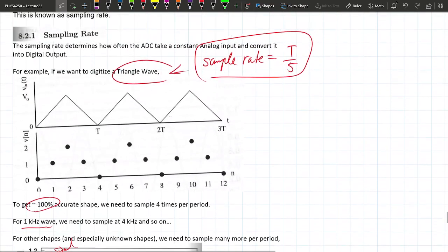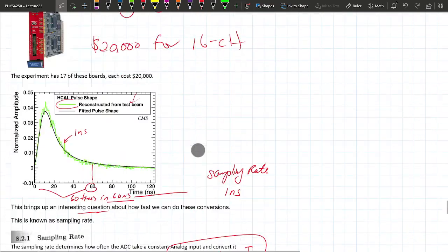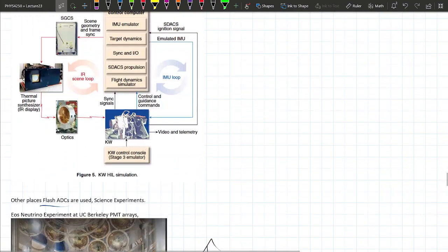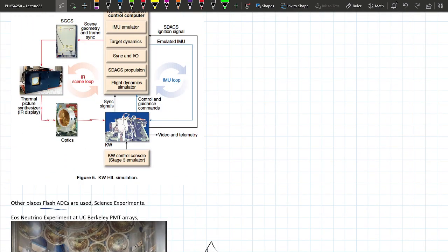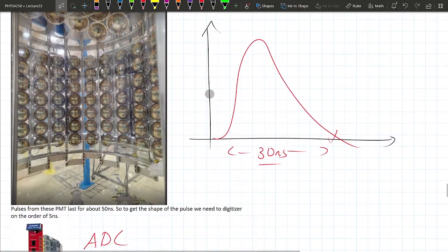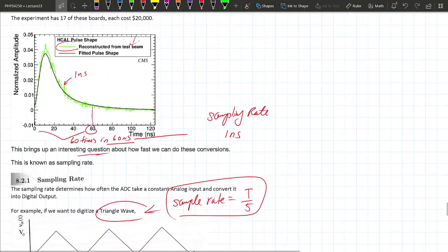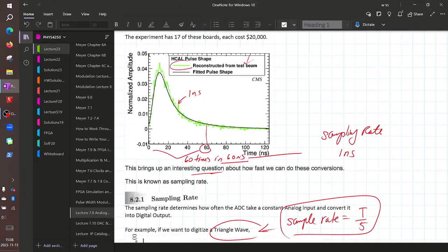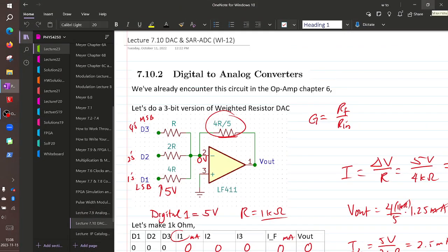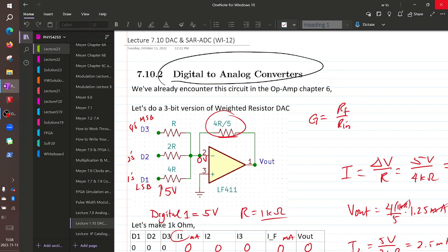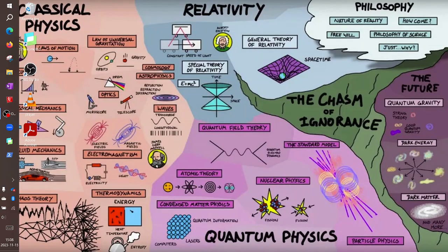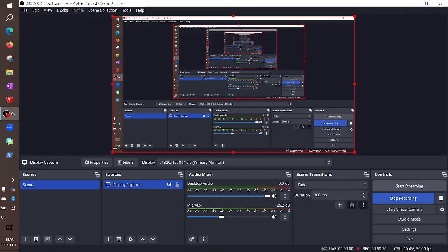Okay. So I covered why we're doing ADCs, how a simple flash ADC works, even though it's the most expensive kind, and what the sampling rate is about, okay? Next time, we're going to talk about how we can cheapen this, so we can put it on our cell phones, right? That's going to be called the successive approximation ADC, but in order for us to learn about that, we actually have to learn about digital to analog converters first, okay? And we'll see why. Any questions?